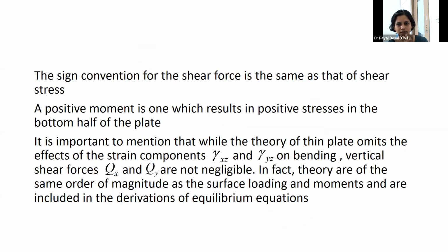Okay, so here the sign convention for the shear force is the same as that of shear stress. Positive moment in plate also is, of course, tension in the bottom, compression in the top. And also it is important to note that though we are neglecting shearing strain components gamma xz and gamma yz, we are not neglecting shear forces. Okay, so this is something like it has an equal magnitude. Just like in beam, we are not neglecting shear force, though we are neglecting gamma xz, right?